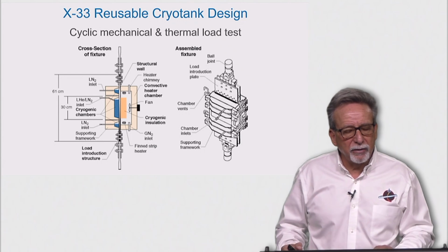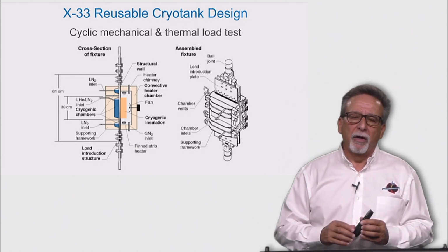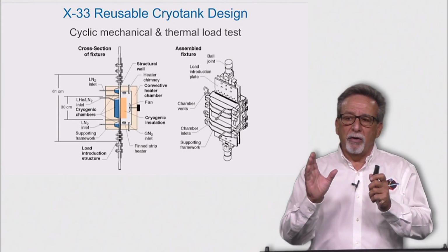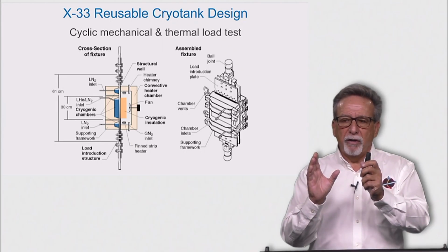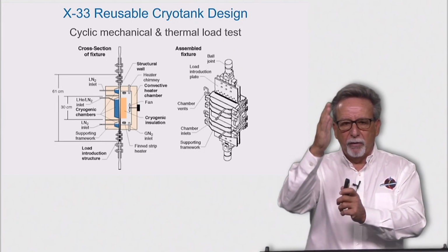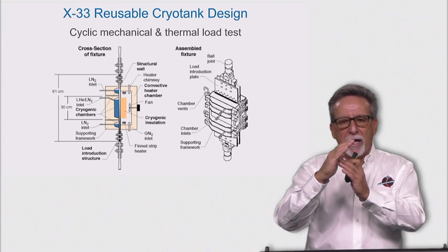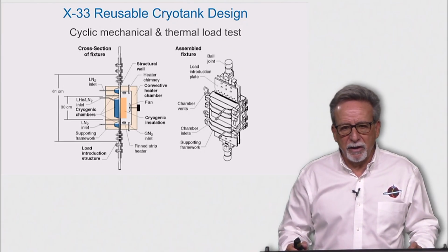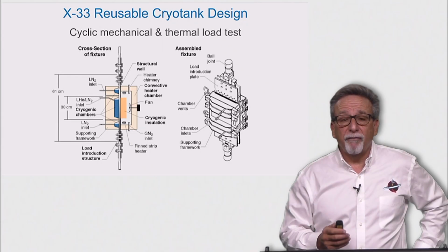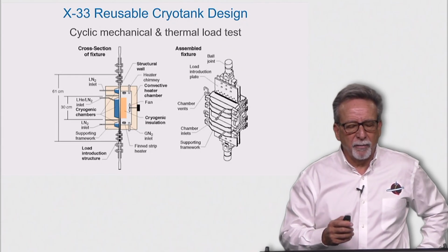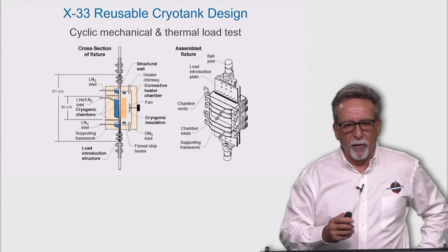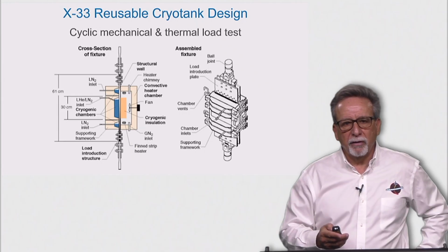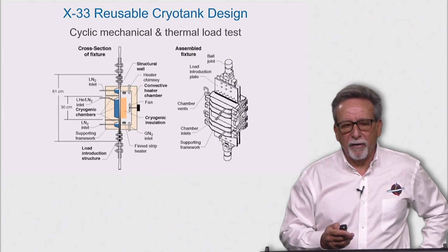So what actually happened was this entire design that Rockwell International was proposing for the cryo tank, where you would bond a silica tile, which is very brittle, to the brittle cryogenic foam. If you did not include that pressure pillowing as you applied the cyclic load, so you were actually bowing and curving the cryogenic foam and the TPS, you would not have recognized that this was a critical failure mechanism. And no amount of densifying the foam or the TPS tile would have prevented that failure, because it was a very low strain to failure material.